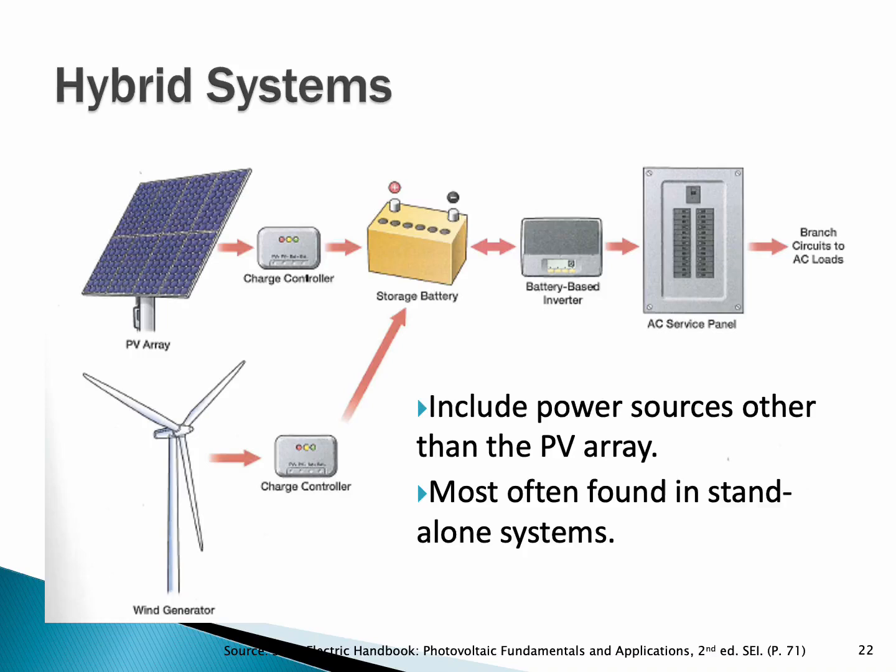So sizing of these types of systems, we're going to take the annual load of the home and run half of that with PV, half of that with wind. So in the spring, summer, early fall, when we have the sun resource, the PV is going to be our primary power source. In the late fall, winter, early spring, the wind generator is going to be our primary source of electricity.